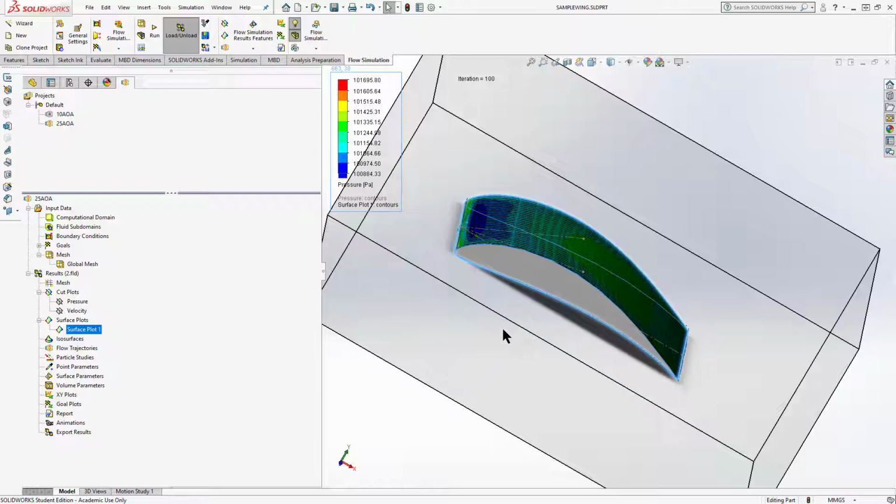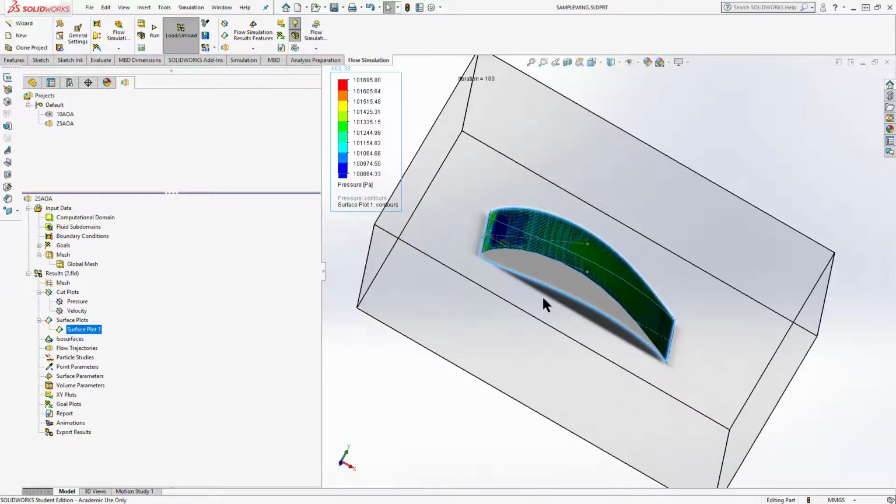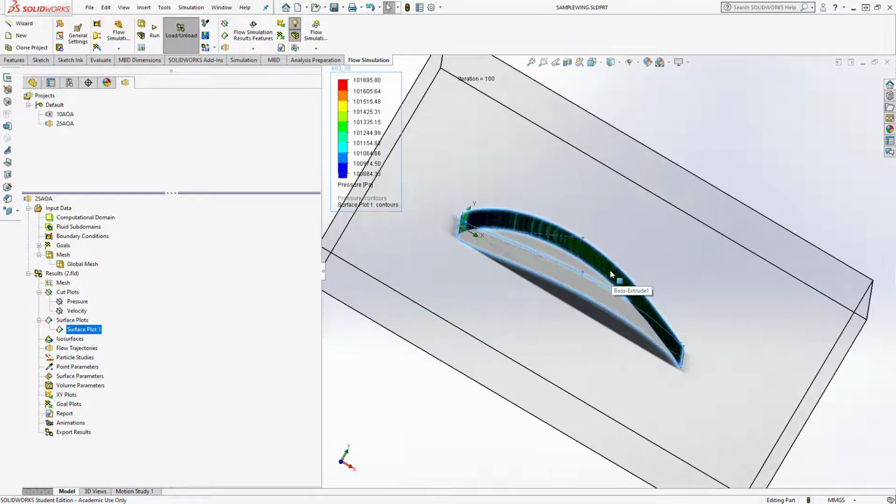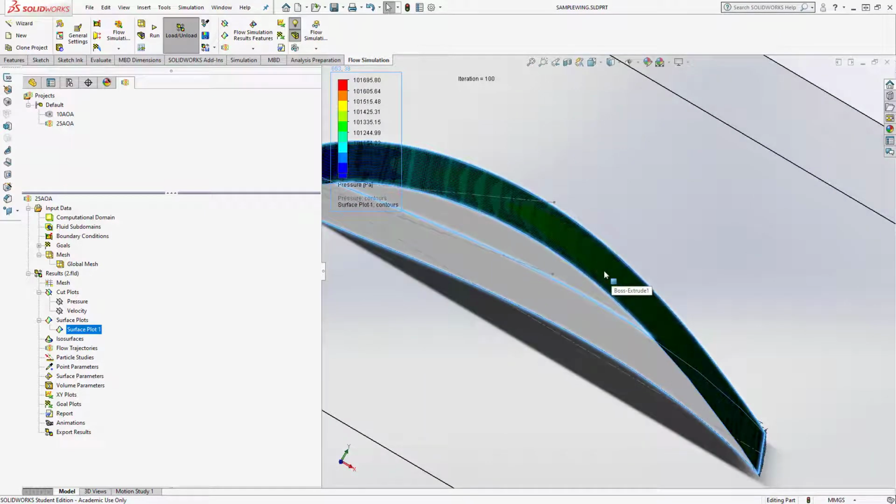If we were to fly those closer to what they're designed to fly at, like the P-51 wing, not designed to fly at 50 miles an hour, more like 150 miles an hour, we'd see more characteristic L over D curves on that. So that's our takeaway. We can now take that exact same project, put it in SOLIDWORKS, and we can predict exactly what will happen to that wing in any condition, even these low, slow flight regimes that we saw in our wind tunnel.